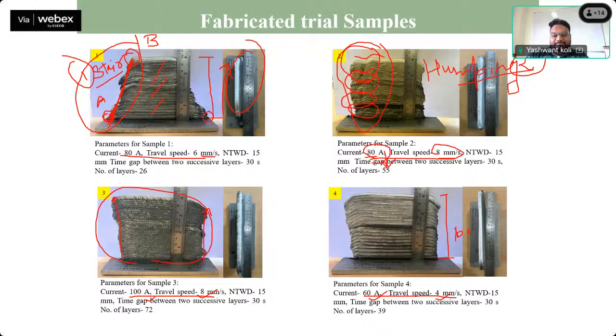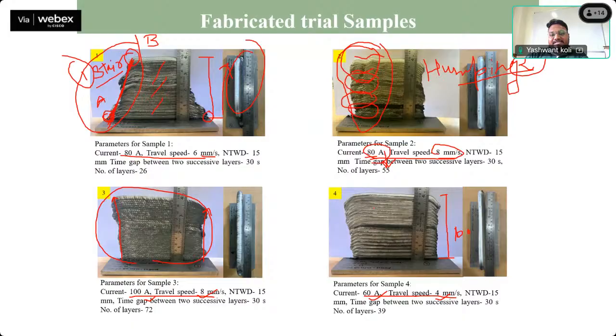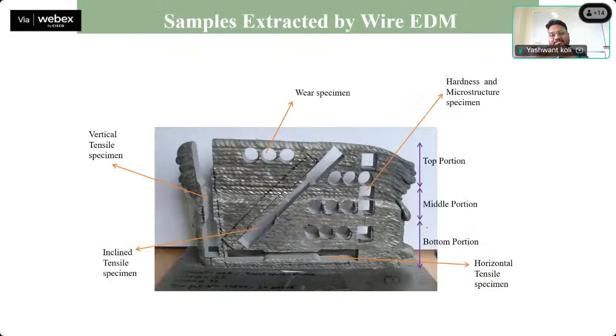The width will be reduced and we can extract the samples. If we are not going for CNC milling, we can extract the sample, then we can go for the polishing process. Because if we do CNC milling operations, some stresses will be formed. If we go for a grinding process to reduce this waviness, some residual stress can also be incorporated. So if we don't want these residual stresses to be there, we can go for the as-fabricated cut.